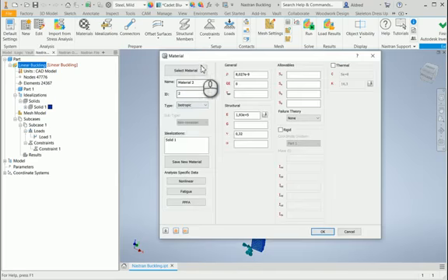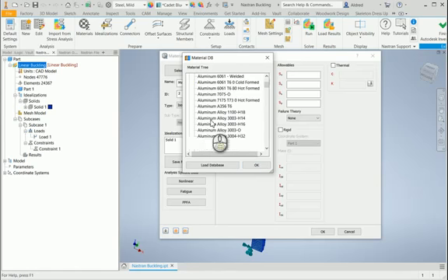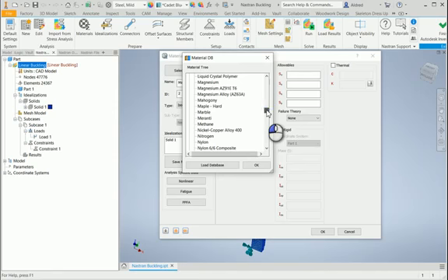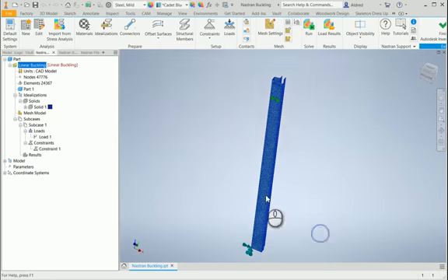The material I've got at the moment is, let's just choose mild steel. Actually, no, let's choose S355. Okay, there we go. So now we've got a material, our fixed constraints, and our loads as well. And then we click on run.